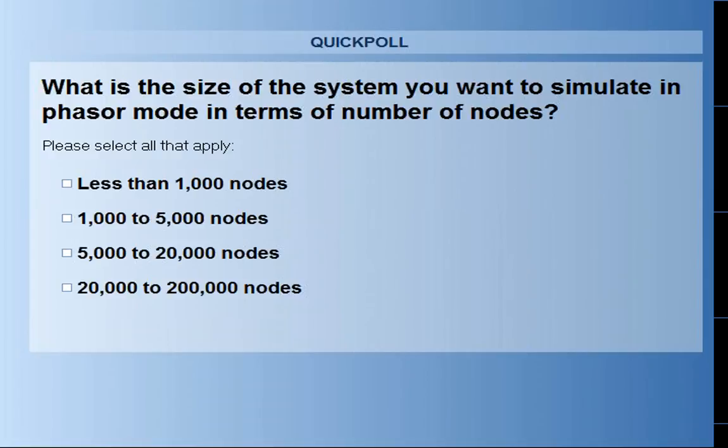First, we can do some data quality checks, data validation and conditioning, and then we can stream the data into power system analytics applications such as mode meter, voltage stability, etc. I'll talk about those later. And then further down, all the raw data and the calculated data will be saved into our database and further provided to the visualization client for the user to visualize.